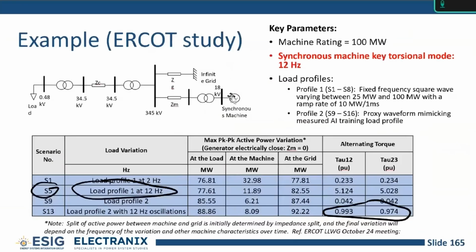Right. So this is something we can see in this test system. In this one, we had this split. They're not ultra low frequency, so they do not necessarily travel too far, but it's very studyable. So in the studies we've done for utilities, I don't have a number for you on how far they travel. It's going to depend on the magnitude and the impedance and the split and everything like that. But they do travel to some extent. It's not ultra high frequency. So if you're worried about 1.5 hertz, it travels pretty far. That's a machine. If it's 12 hertz, it will not be as far. But